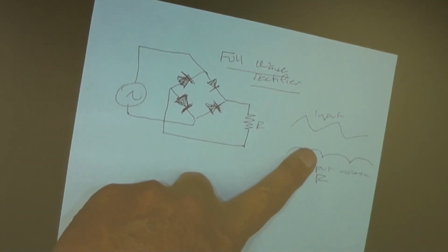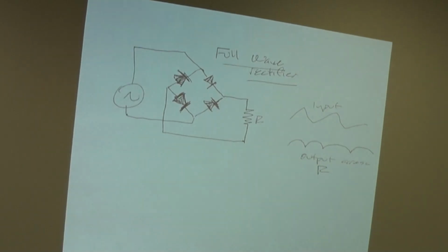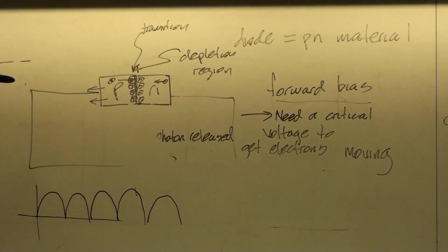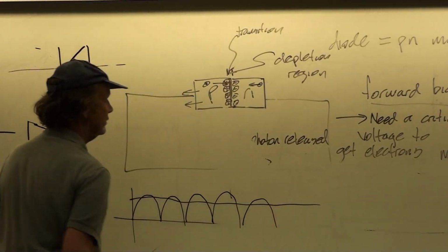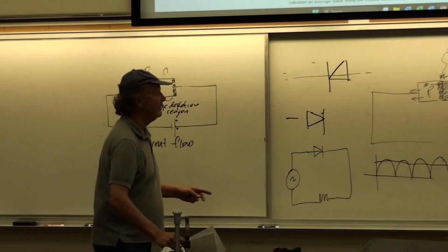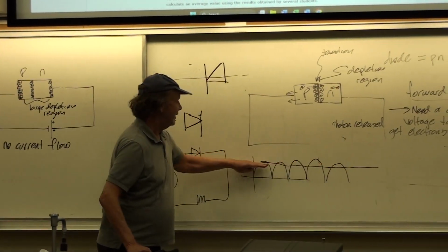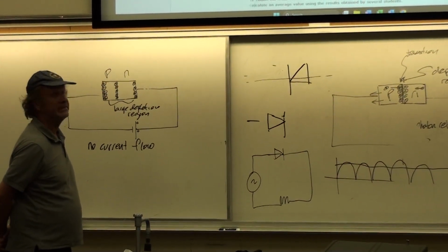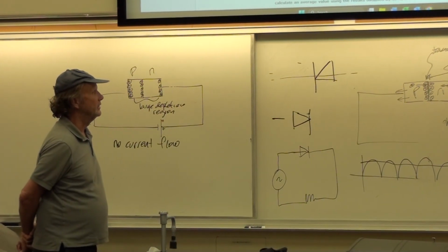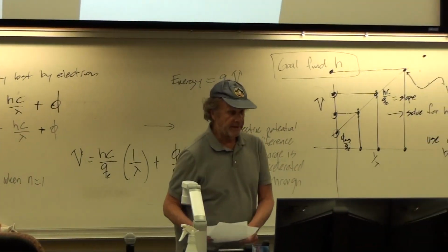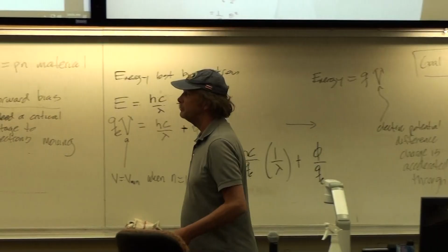It's pretty clever. So that's one of the techniques for turning AC into DC, is to first take the absolute value of the signal and then smooth it, like with capacitors and inductors and stuff. And depending on how good your converter is, that can give you a fairly stable DC-like signal from an AC source. Any questions about that?